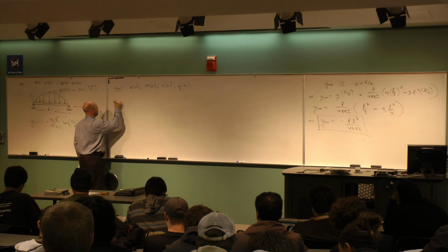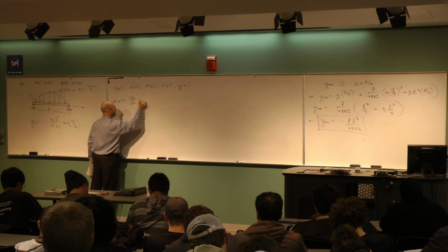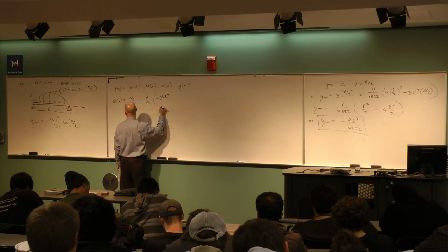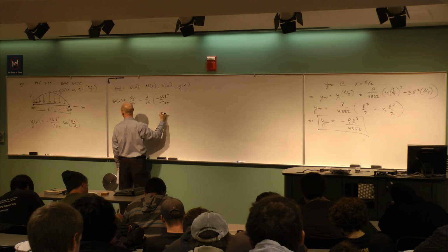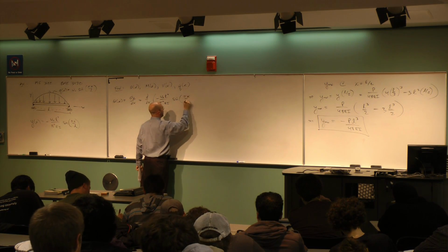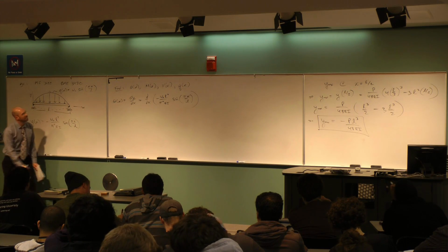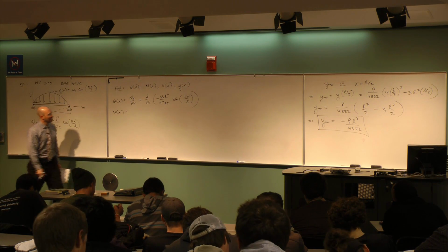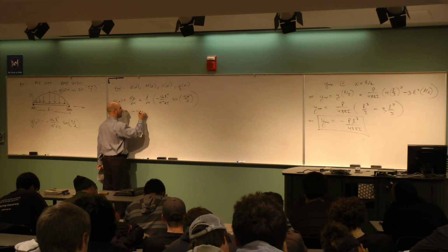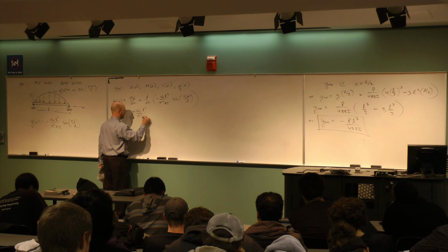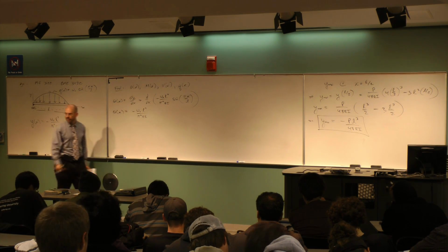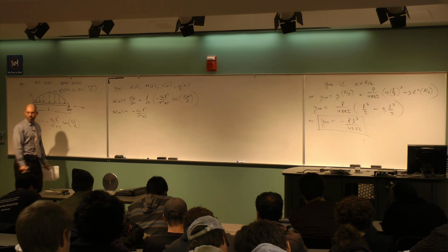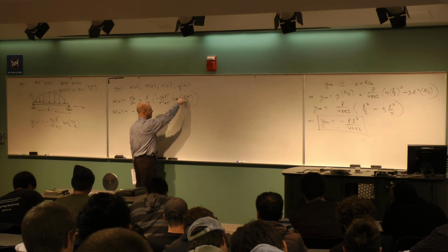So theta of x, by definition, is dy/dx. So I want the derivative with respect to x of the given function, minus w naught L to the 4th divided by pi to the 4th times EI, and then I've got a sine function, pi x divided by L. Help me out. What do I do with the letters in front there? These guys are constant, right? So the minus w naught L to the 4th divided by pi to the 4th EI just sits there. And now I need the derivative of the sine of pi x over L. Derivative of sine gives me what?